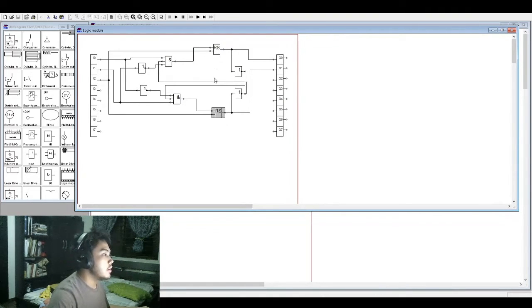So the logic circuit for each input is wired onto the latching relay block. Here we wired the logic circuit for the first input, which is PB1, and on the other relay latching block, we have wired the next input, PB2, the logic circuit of PB2, onto the other latching relay.